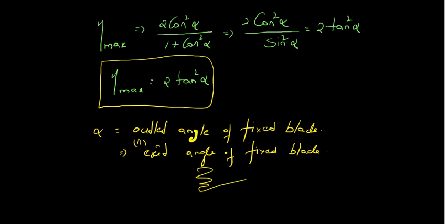And from this relation we further calculated the mass flow rate, and the mass flow rate is given in terms of the volume of flow multiplied by the dryness fraction divided by the specific volume of the steam for that given section, right? And even this h by d means the height of the blade, and d is the diameter of the wheel. What is the relation between the mean diameter and the diameter of the wheel? The mean diameter is the summation of the height and the diameter of the wheel.